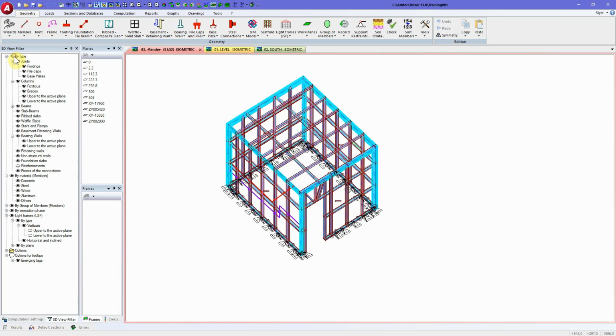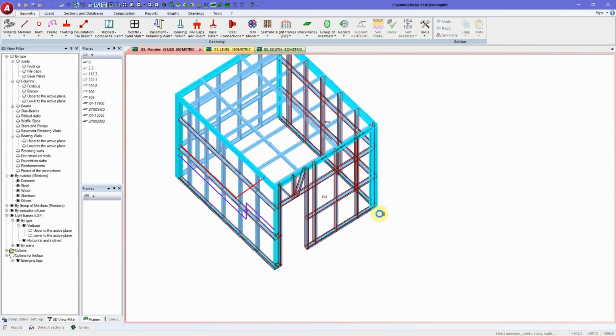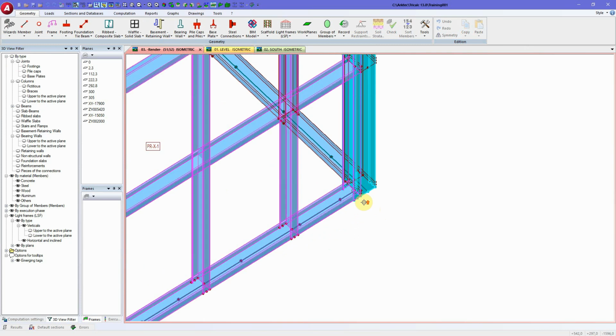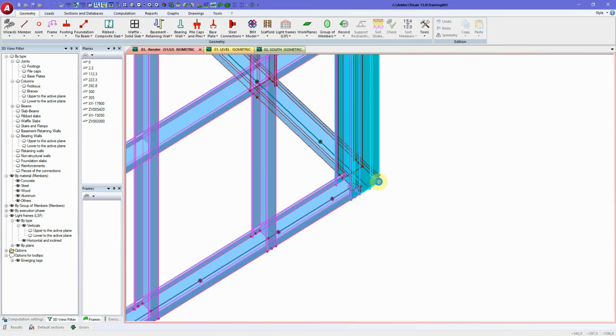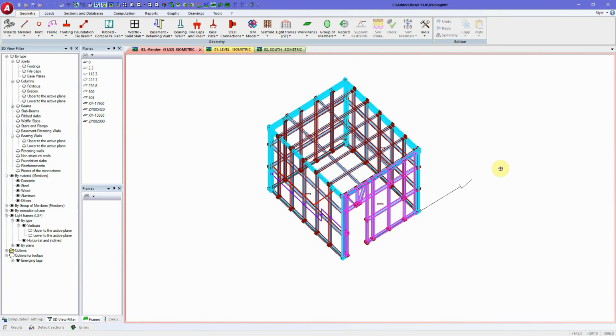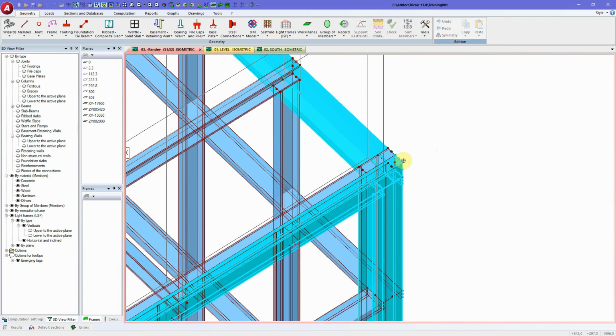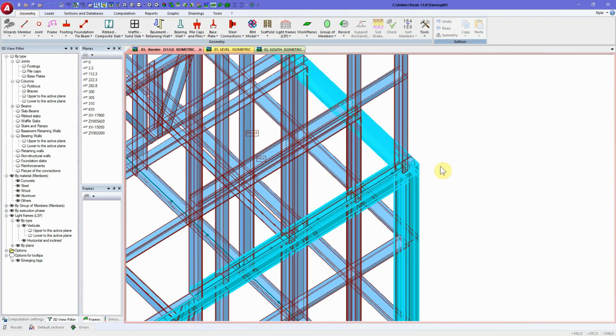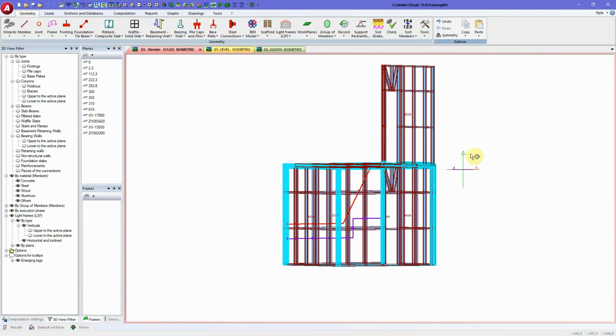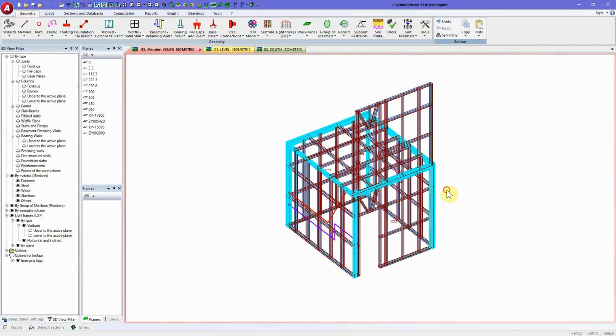I'm going to disable here the structural elements. Just copy the frame here and escape key, define the insertion point. Let's say this point here. And if you want to set up a direction, you can set it up now, but I don't want to use any, and escape. That direction will be helpful if I want to paste and rotate. Okay, I just want to paste simple and define the insertion point with no need for rotation. If you need rotation, you need to define a direction. So it is a new panel created over the slab.